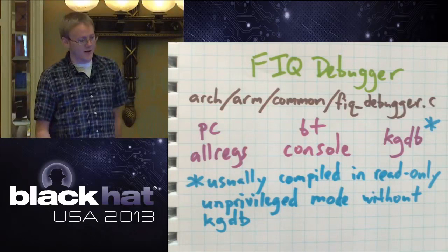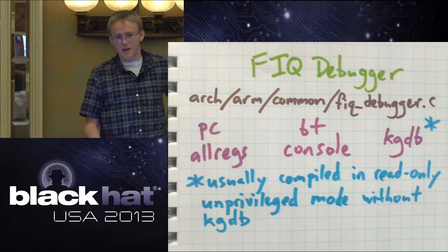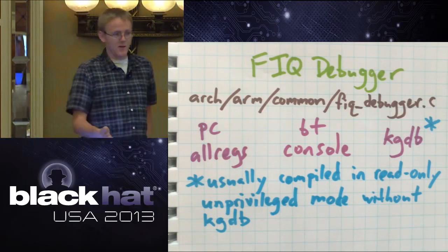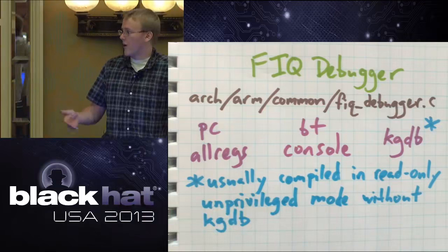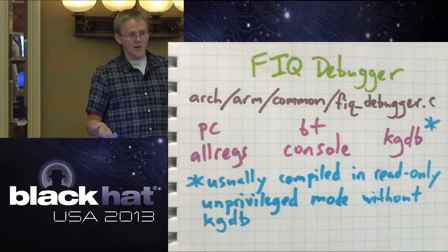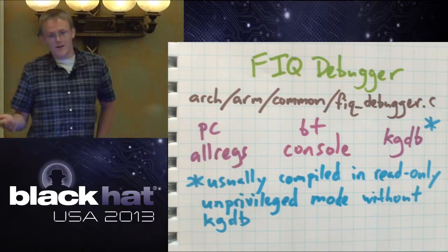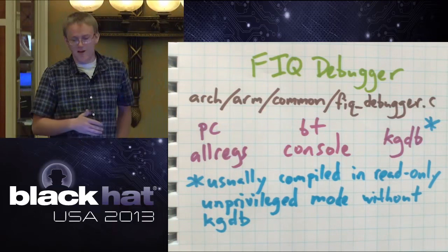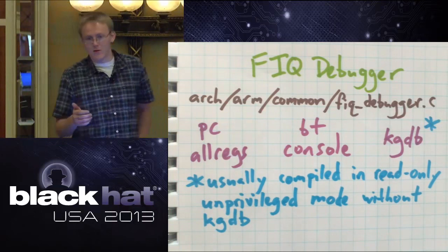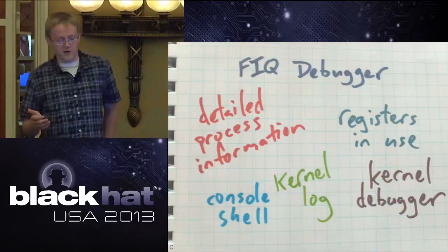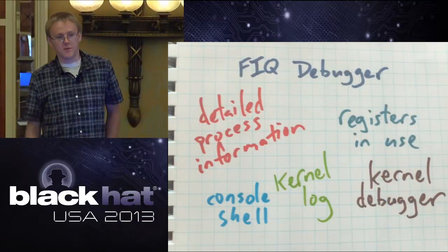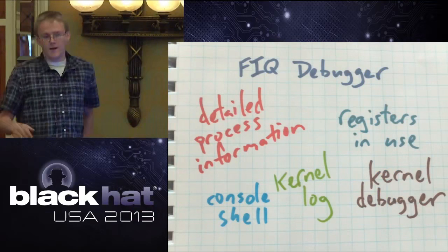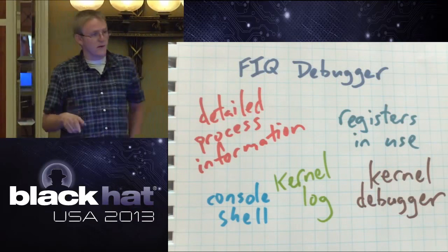Because if you have a kernel panic and you can't use the USB connector, because that's part of the kernel and that's a USB driver, or some other method to access it is unavailable, or ADB is an application, a service that runs, and if the kernel freaks out, you can't access it. So they have this, which actually will provide plenty more information before everything kind of just goes kaput. And it also allows you to access other things. You could potentially push updates to it, or write firmware with it, and other types of things. A kernel debugger is included with this if compiled with it.